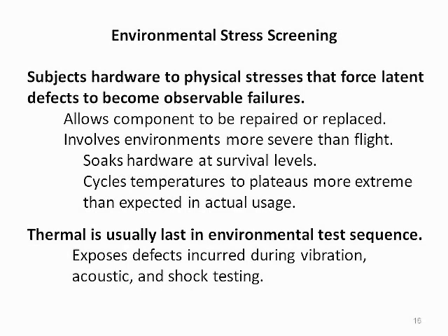Thermal testing is usually the last test in the overall environmental test sequence because defects and weaknesses introduced by vibration, acoustic, and shock testing are more likely to become apparent through full functional testing performed at extreme temperatures.